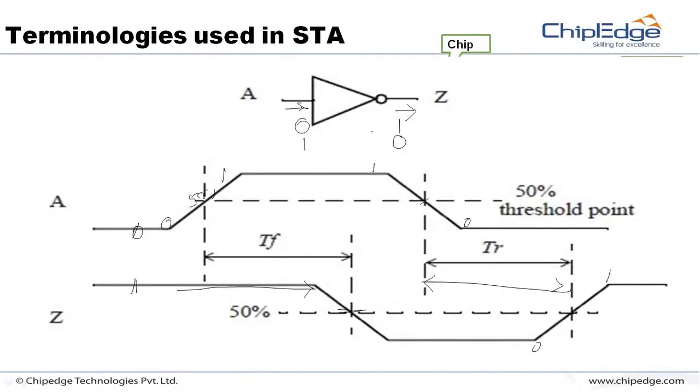I can talk more about these standard cells. See, the standard cells like inverter, AND gate, OR gate will come from something called a standard library. So people are talking about technology, right? They say 28 nanometer, 65 nanometer, 10 nanometer. What does that nanometer mean? You know, an inverter is made up of two MOSFETs, one P MOSFET and one N MOSFET. This is your inverter, right? This is your input and this is your output, and this is your VDD and this is your VSS, the ground.